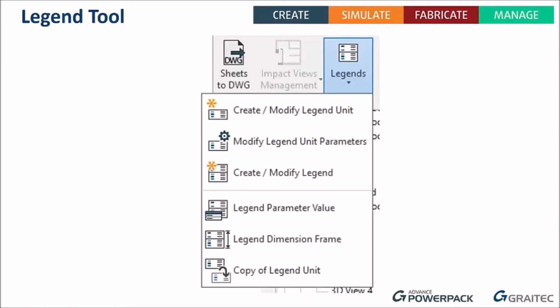Why couldn't I just use a schedule tool that listed all the different types of doors that are in a project and do it for me? A bit like a schedule. And it amazed me that Revit didn't do that. So when we developed this tool, I was very, very happy, because that is exactly what this does. This basically helps us to automate the creation of legends inside of Revit. So as I say, these are the various different things we have to do to start with.